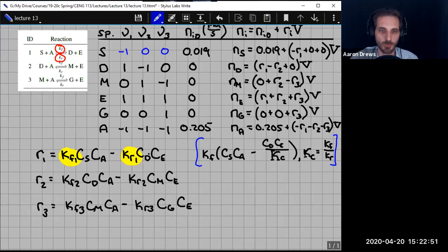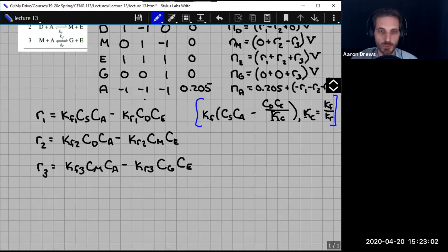So we don't have too much of a problem there. And we need to know how do we connect the moles, for example, the moles of the soybean oil to the molar concentration of soybean oil. Fortunately, we're dealing with a liquid phase system, so that conversion is fairly easy. So in each one of these, the concentration of any species i is always the molar flow rate of i divided by the outlet volumetric flow rate. So that's the lowercase v.